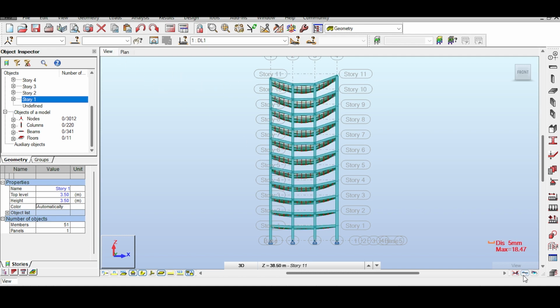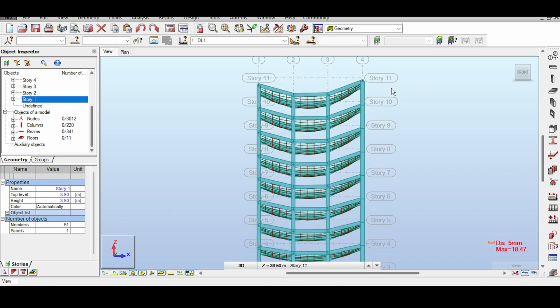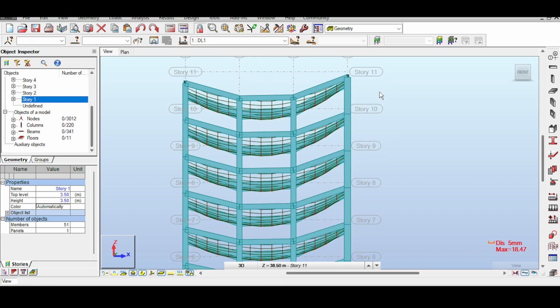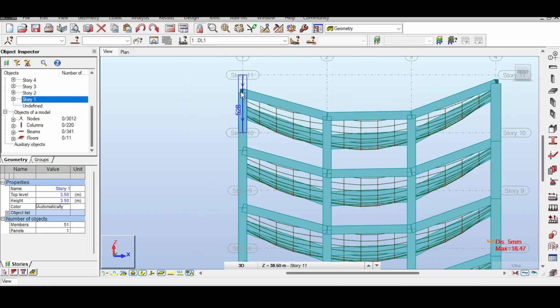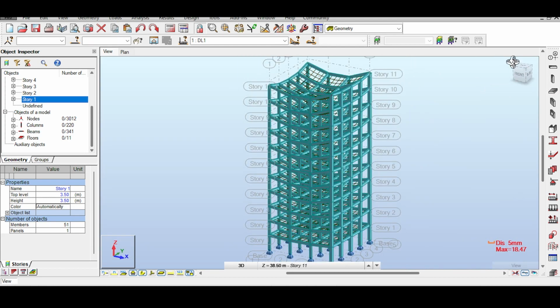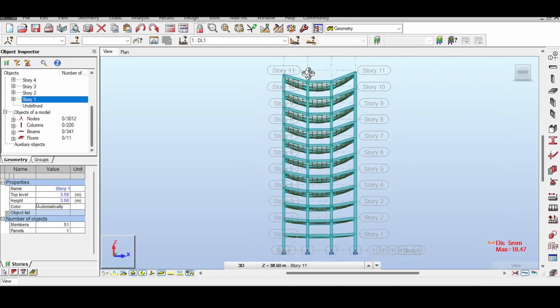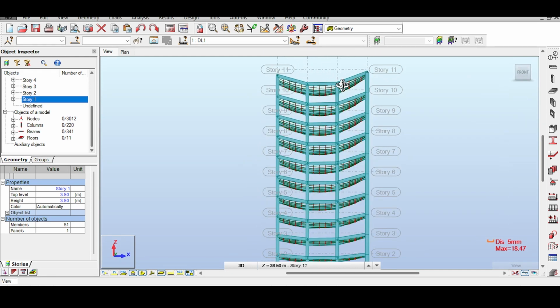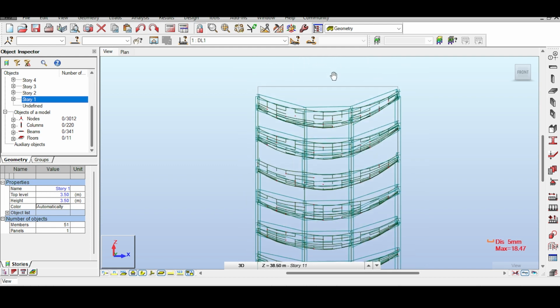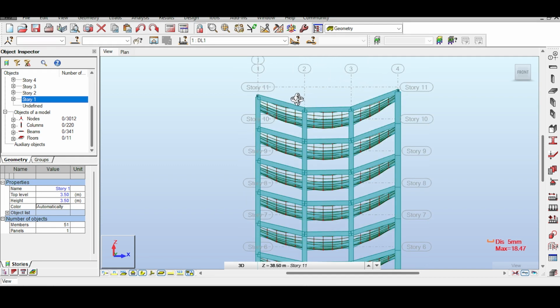So if I go to deflection, you can see the structure, although it is unsymmetric, suddenly the structure doesn't lean. There is no leaning in the structure. But you can see that the column on the left side is going further down than the column on the right side. However, there is no leaning in the structure. Why is that? To understand why this is, I want to make something very strange. Because it's somehow obscured with the bending of the beam. But what happens here is actually that if the beam is infinitely stiff, you would have a line connecting those two things because it's released here.